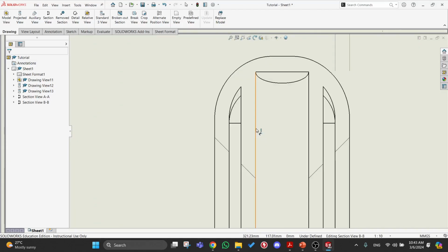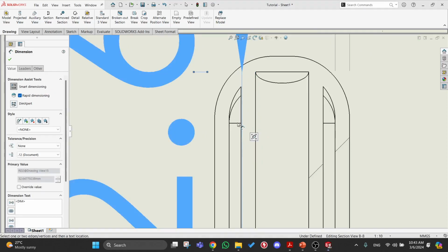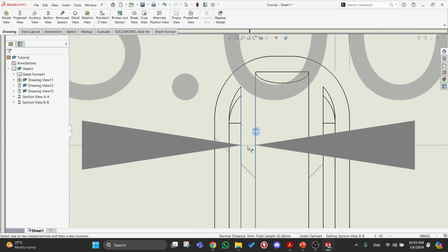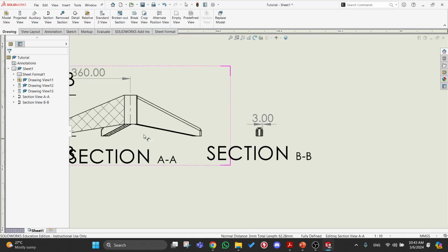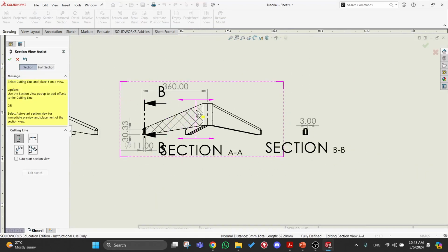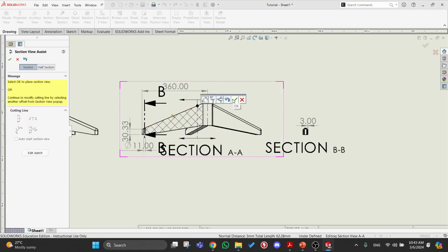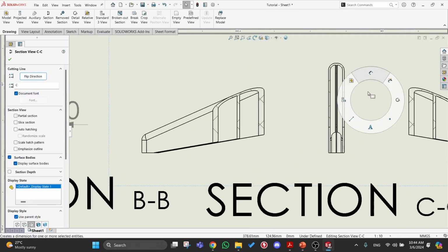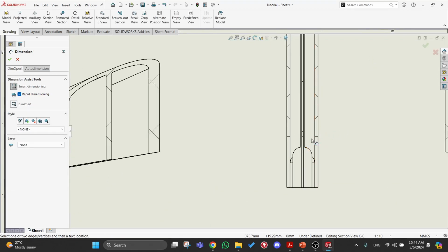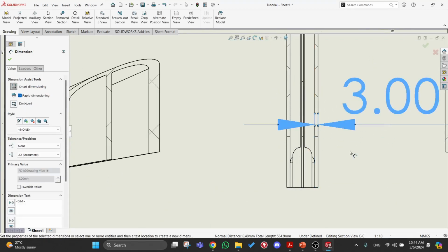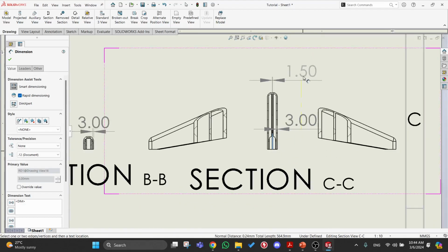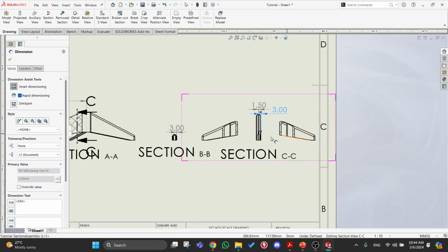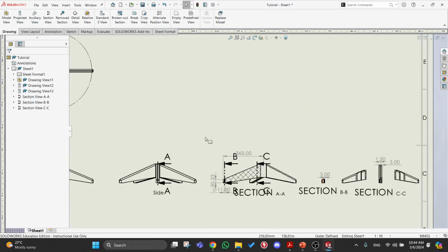And you have your ribs. This is not your ribs, this is also a nominal wall. To get your ribs you need another section more behind. This is important because you want to check your drafting later, so you need to do this as well, right? Ignore the other sections. We need to find out, this is still 3, right? Yes, it is 3. This is the middle part here, 1.5. It is 1.5. Great. Okay, so you got your thickness correctly.